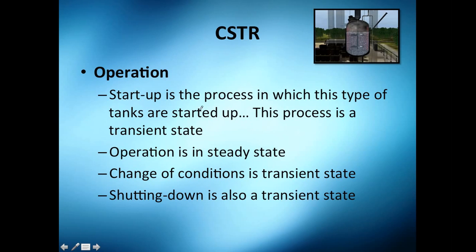Now there is a startup in the process. So essentially the process is in transient state. Of course, if you have an empty CSTR because you're going to start it up, you will have to reach a certain level of liquid. That's going to take time. That's why it's a transient state. Also concentrations, also temperatures. You're going to heat. Maybe the tank is at 25 Celsius and your operation temperature is 300. So you're going to have also a transient state in energy. And yes, essentially that's the startup.